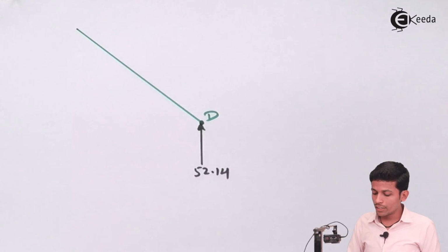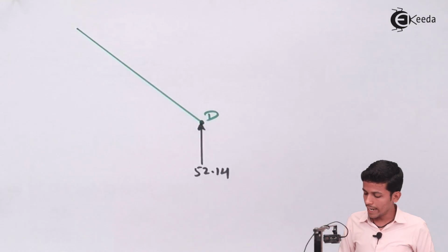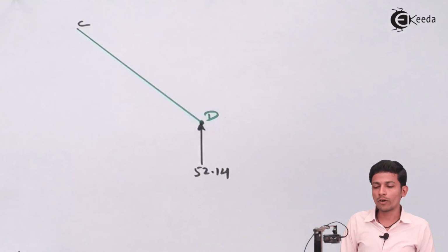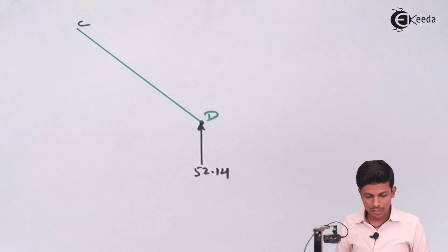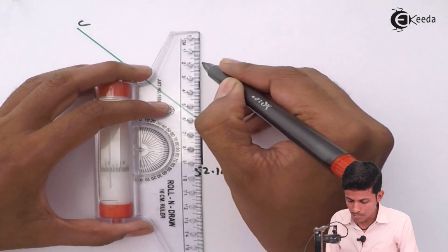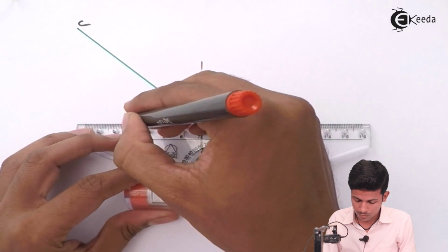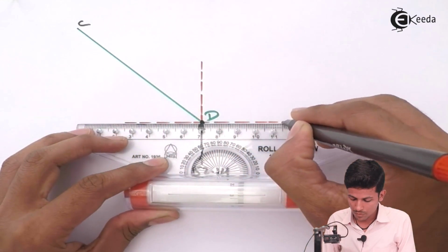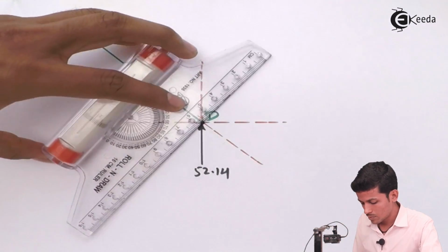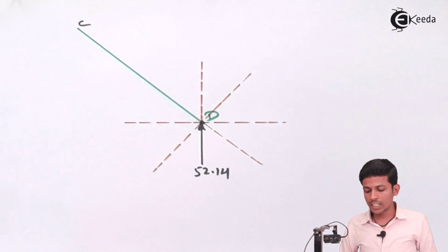But here we don't want the vertical direction, we want the axial of C and D, and the vertical of C and D. For this we have to resolve. Now how will it resolve? See, to resolve this part, extend all the members as much as possible like this. Okay, now we have extended all these parts.